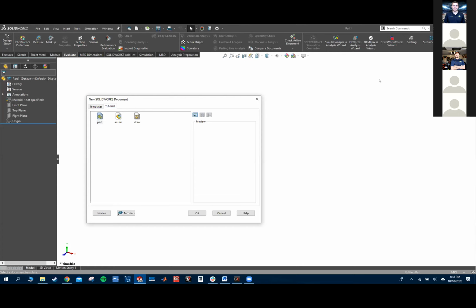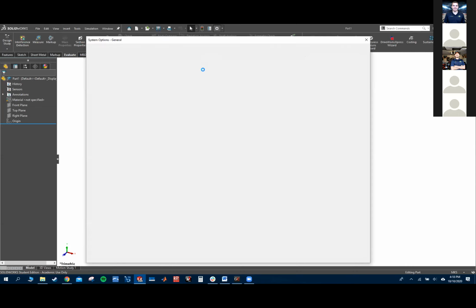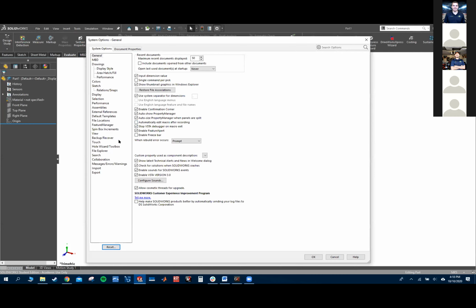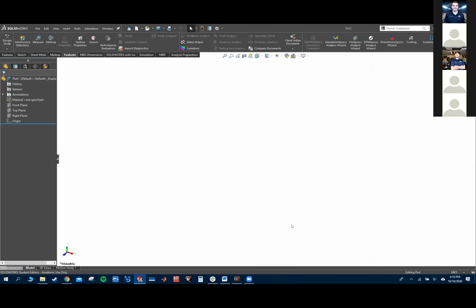And once you do, you just click on the settings here, and you have to point it to the file location. But we'll come back to this when we have those templates ready. This is where you would do it. See, right now it's pulling from the SolidWorks installation file location. And later I'll show you on my SolidWorks when we switch to my computer how it looks.